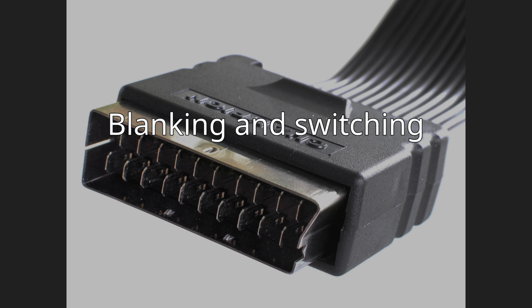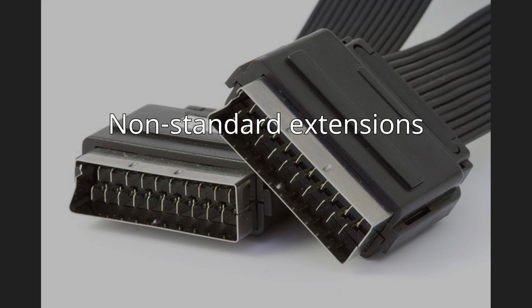There is no switching signal to indicate S-video. Some TVs can auto-detect the presence of the S-video signal, but more commonly the S-video input needs to be manually selected. The same goes for the rare component YPbPr, which is in many cases implemented over a composite or RGB Scart. Non-standard extensions. The use of the data pins was not standardized in the original Scart specification, resulting in the use of several different protocols, both proprietary protocols and semi-proprietary protocols based on standards, such as D2B.